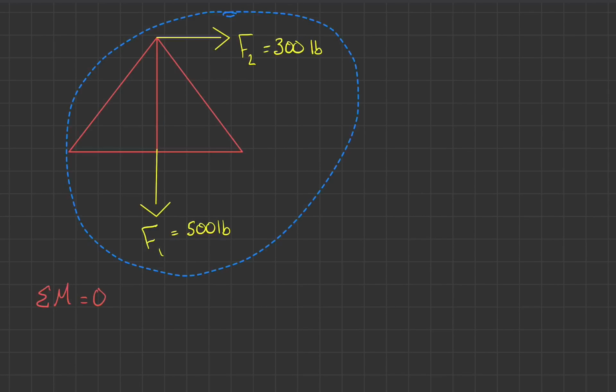Okay, so we had a pin joint at A here, so this was A. So now we're going to solve for the external forces. So we had a pin joint here, so that's going to have a vertical force and a horizontal force acting on it. And then we're going to have a roller joint here at C. So that's just going to have a vertical force.